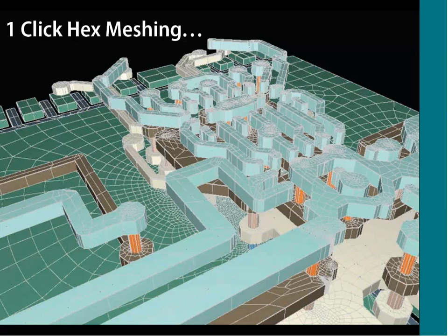We have different automatic meshers, so that no matter where in IntelliSuite you're developing your model, you can automatically mesh it. Say you just want to import the layout for your model that you've already developed and input what the thicknesses of the different layers are going to be, you can automatically mesh a model that way. If you're developing a process traveler within the virtual fabrication tool and you develop a 3D model that way, you can export and automatically generate a mesh.